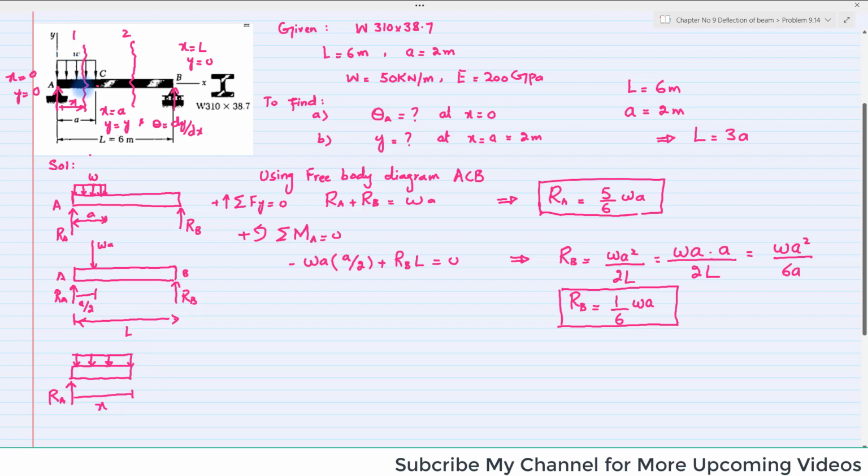So if you cut the beam over here, there will be a shear force V and a reaction bending moment. Let this point be point J. Clear? This is the portion of beam for which x is greater than or equal to 0 and less than or equal to A. Clear? So we will use this first.